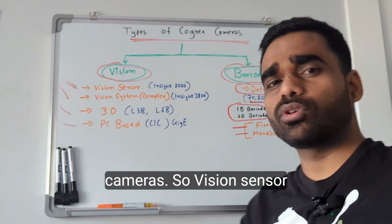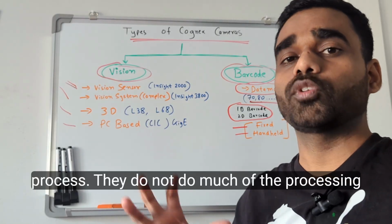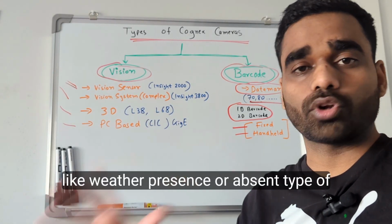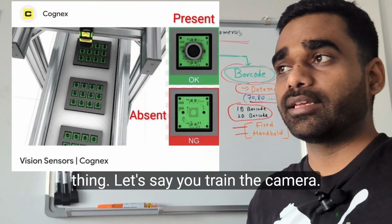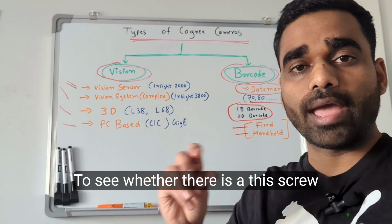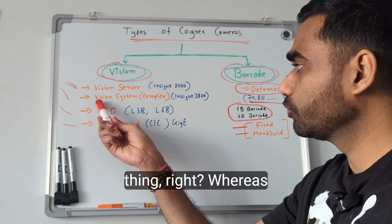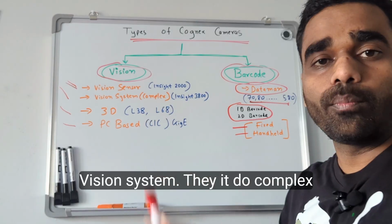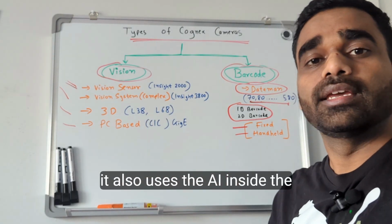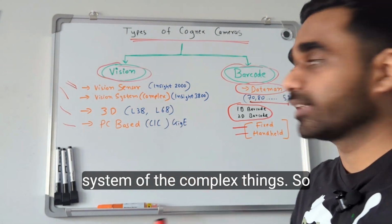Vision sensors don't do much processing inside the camera. They are just used for presence or absence checks. Let's say you train the camera to see whether this screw is absent or this screw is present, right? Whereas the vision system does complex processing inside the camera itself. Sometimes it also uses AI inside the camera for the complex vision tasks.